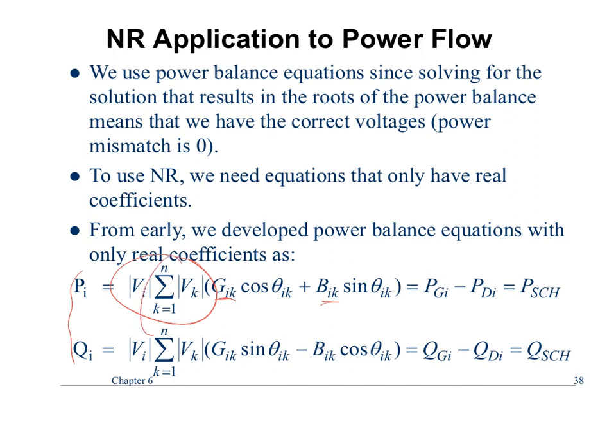K is part of the summation. So anytime you are connected to bus i, bus 2, bus 3, whatever, your value of K is going to go from 1 to however many buses you have in your system. So if you're doing PSSE, ISO New England territory, you've got 80,000 as your value of K. So your summation contains up to 80,000 elements. It won't.